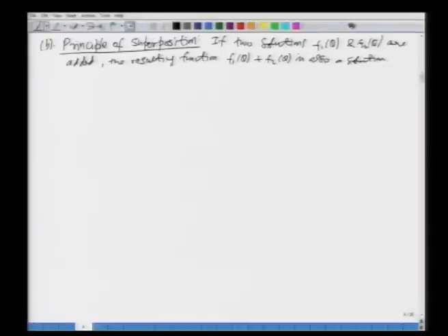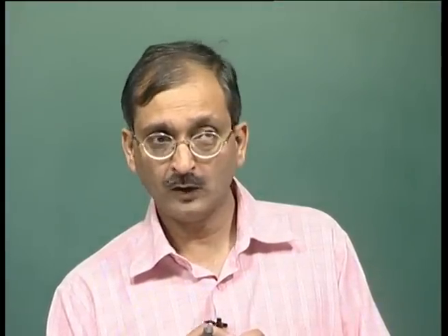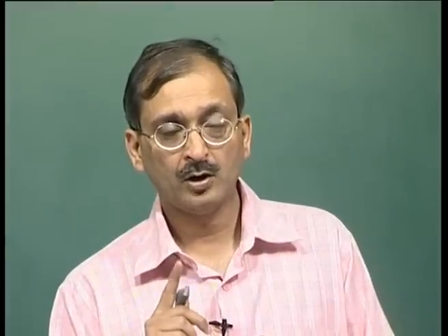So, if we look at the principle of proportionality first, it allows us to find out the direct runoff hydrograph from a certain amount of rainfall. What is a unit hydrograph? I am going to look at the definition very quickly here, because I want to demonstrate the proportionality principle. A unit hydrograph is nothing but the direct runoff hydrograph response from a catchment due to unit effective rainfall.